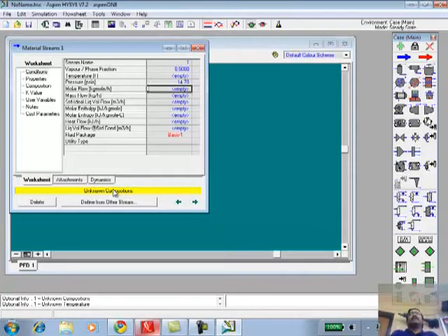Well, if you had bends in the pipe, wouldn't that affect it? It will affect something. What would that be? Well, you could have expansion bends. Or if you have a certain length between two process units, you can simulate that. If you're transferring the fluid from one unit to the other, you could lose heat to the surroundings. So the temperature that comes out at the end could be different from what you put in the pipe. The pressure will also certainly be different.